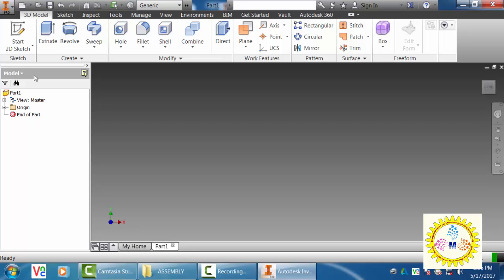Done. So I need to create a part in such a manner that, for example, the x plane is your horizontal plane and the y plane is your vertical plane. If you select the y plane and finish off the sketch, the complete model will be standing vertical. Normally if you observe the body of the screw jack, it is standing vertically, right?